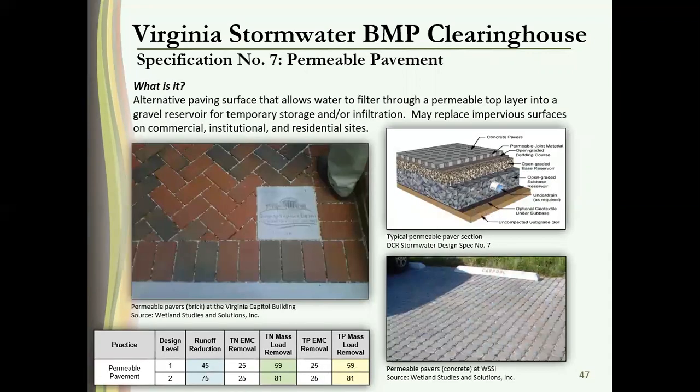Rainwater harvesting has an additional design component to it that you have to consider. The VRM spreadsheet is really good, basically plug and play, to figure out your treatment. But for rainwater harvesting, there's actually a whole other spreadsheet that you have to use. That's just an FYI. So you have to think about how much rain, how big is my tank, stuff like that. You gotta give it a little more consideration.